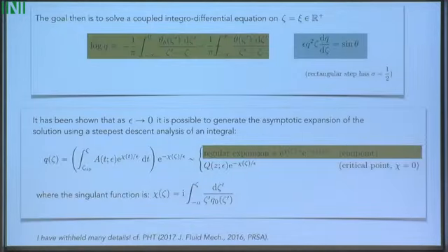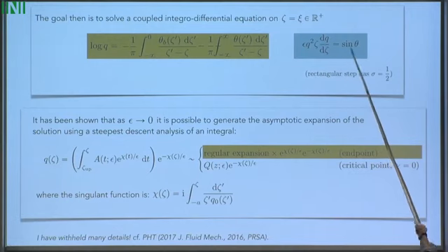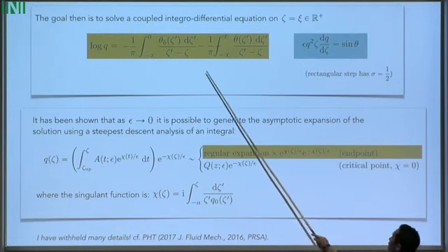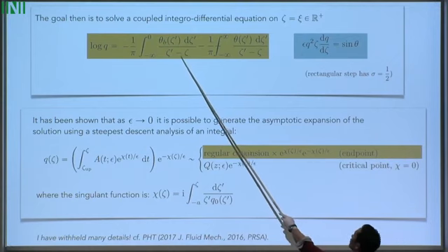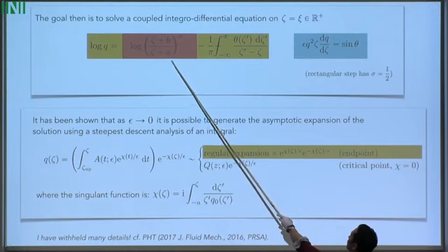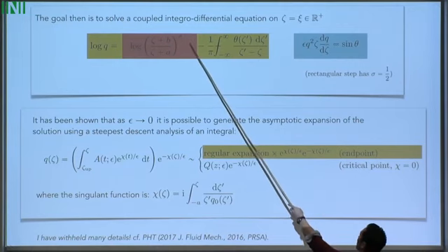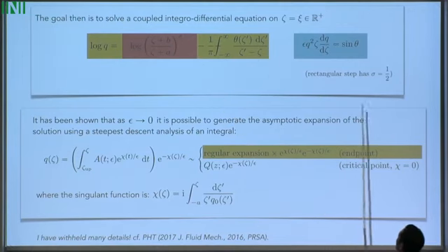The equations are essentially Bernoulli's equation on the free surface for the speed q and the angle theta, and then a boundary integral equation here, but you know certain details of the angle on the left side because you're specifying the angle there, so you're able to write that down analytically. So this is just for flow over a step with a certain angle parameter sigma. When sigma is equal to a half, you have the rectangular step. So this is the type of problem that you can solve numerically. Okay?